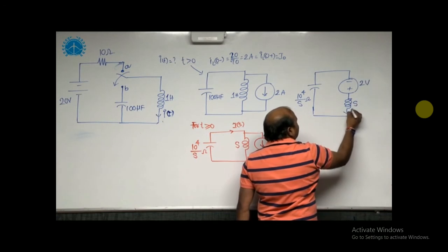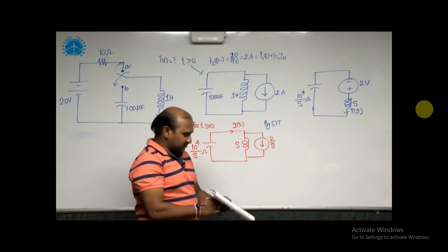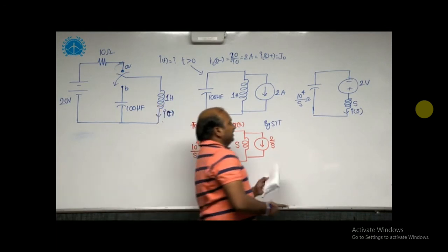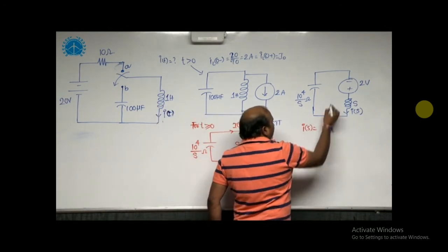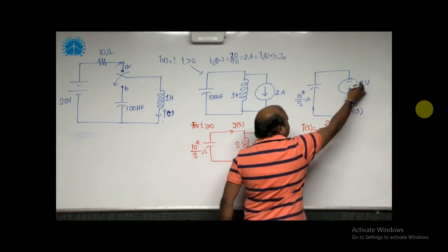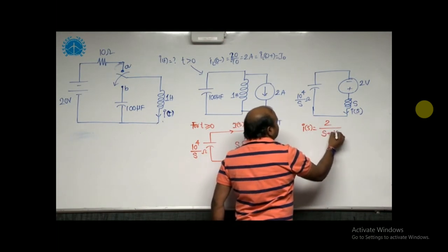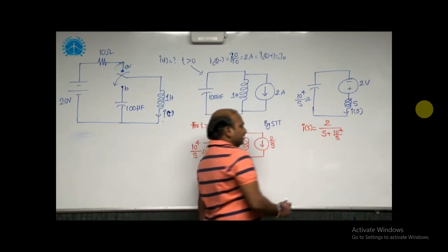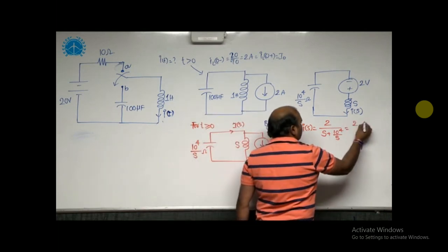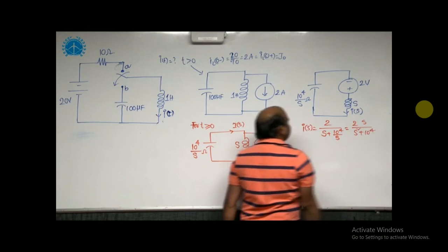According to the given current direction, and this is I of S, and the voltage source polarities both are the same, that's why I can take the I of S value is equal to the applied voltage, here 2, this voltage source value, by the total impedance S plus 10 power 4 by S. With this you can take it 2S by S square plus 10 power 4.